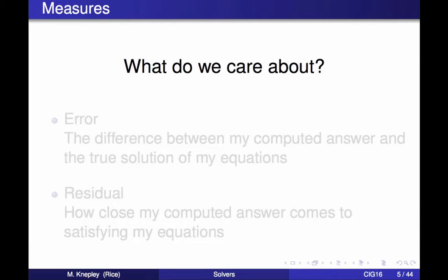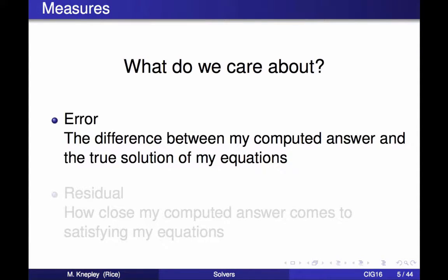Even simpler to assess, I would say you care about error. What's the difference from my computed solution to the true solution of my set of equations? Okay, that's the thing I think you would really care about. You wrote some equations, you ran a piece of software to solve them, you should be interested that it gets close to the true solution of the equations that you wrote down. That says nothing about how close the true solution of your equations is to reality, but this is all that PyLith can maybe promise you.